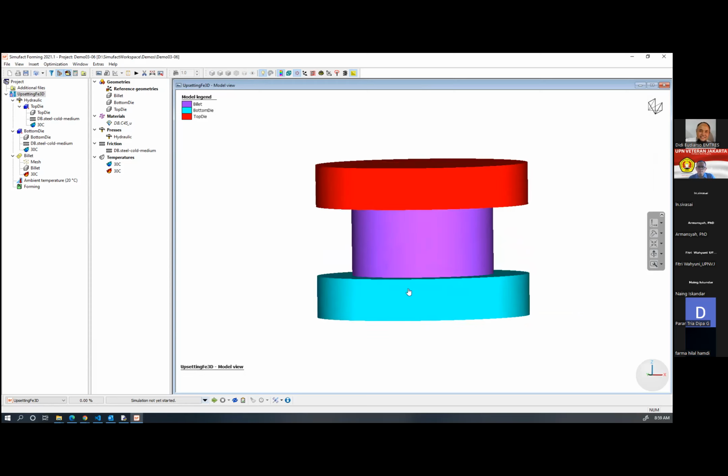So all the things are satisfied, but one thing is left out. In finite element analysis, the first important factor is mesh, domain discretization. So now I just need to create this mesh for my workpiece. Since our tools are non-deformable, we don't need to create mesh for them. We need to create mesh only for the deformable entities.